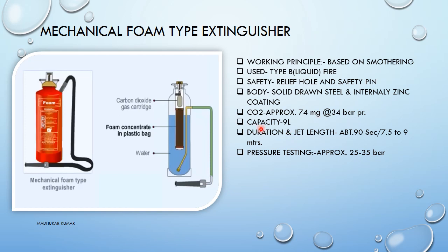Capacity again 9 liters. Duration approximately 90 seconds. Jet length 7.5 to 9 meters. And pressure testing is done at about 25 to 35 bar pressure. Okay, so this is all about your mechanical foam extinguishers.